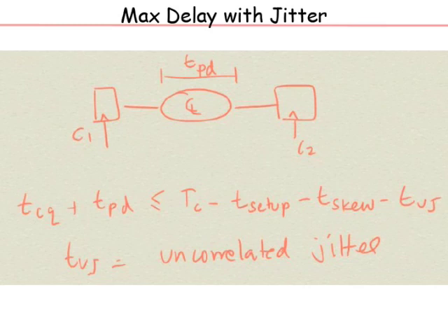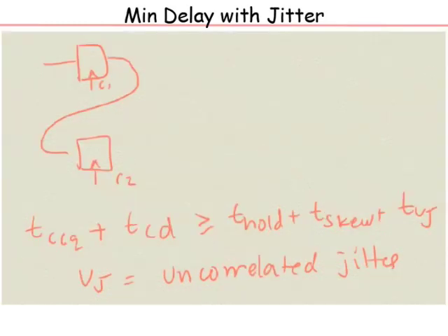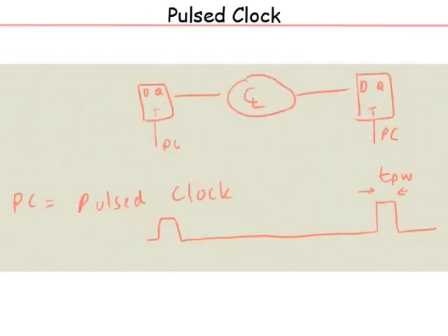If you lose a fan out 4 to clock-to-Q and another fan out 4 to clock setup, you just lost 2 out of 12 just for going in and coming out of a flop. That is a lot of overhead. So clock distribution, sequencing, and choosing the right clock become very important for very high performance designs. That is why people started using pulse clocks.